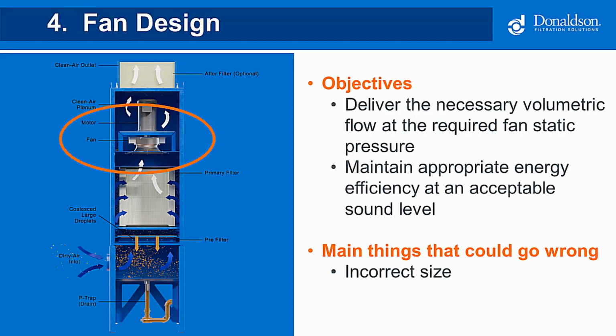Now, mist collectors are unique to most other types of collectors in that a lot of the fans are integrated into the collection system. These are typically designed for point of use or minimal duct runs. When you're using a cellular or central design approach, as we discussed earlier, you need to be careful when using integrated fans and evaluate the total system static pressure to make sure that the integrated fan can meet the requirements of the system. If it cannot, and in some cases it doesn't, you'll need to use a custom fan or a specially designed fan for that application.